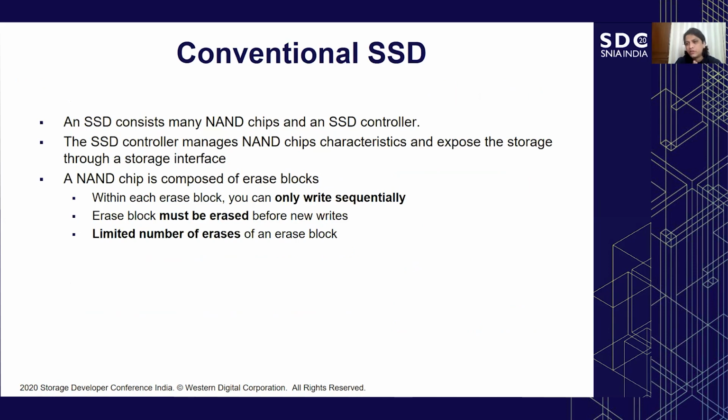Okay, so we just saw the characteristics and specialities of ZNS, and now just to get an idea of conventional SSDs. In a conventional SSD, as with a ZNS SSD, they have NAND chips, and the SSD controller manages these NAND chips and exposes the storage through a storage interface.